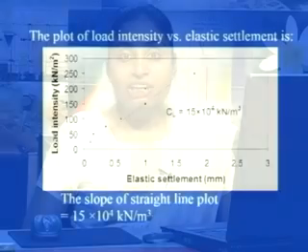In case of test plate, the test plate is of a definite size, like 30 centimeter by 30 centimeter. However, the area of the foundation can be quite high, and in the statement of the problem it has been given that we have to get these coefficients or constants for base area of 10 meter square. However, the base area of the test plate is 0.09 meter square.